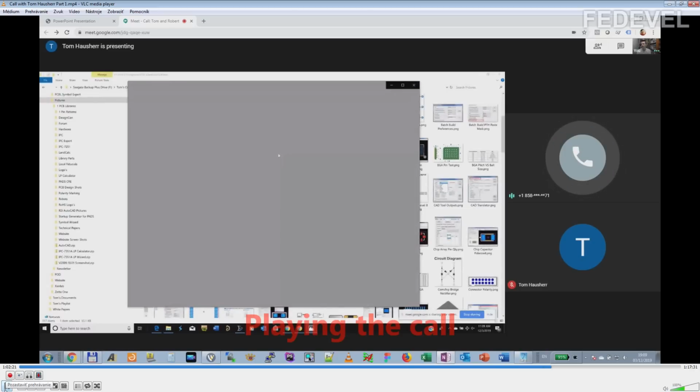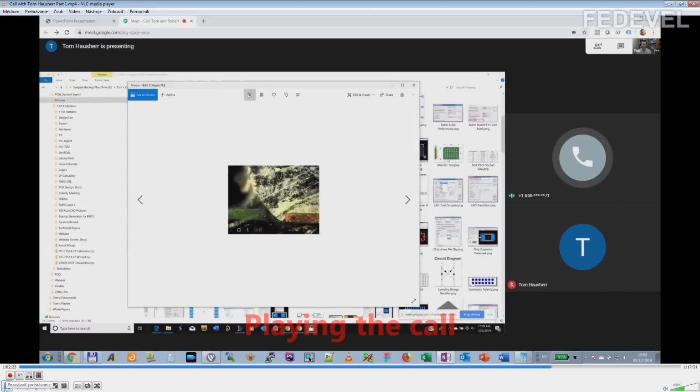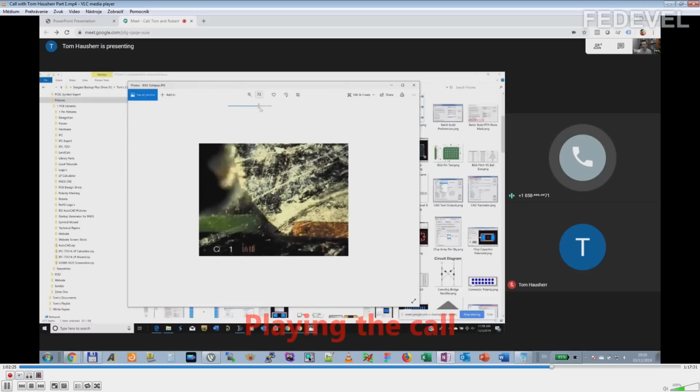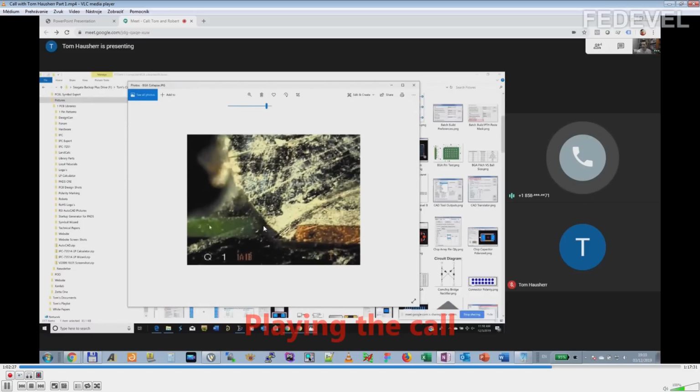You want a BGA to collapse around the pad, so you have here your solder mask, your green solder mask, okay, and your pad is much smaller than the ball, okay. And when you go to the oven, you want the BGA to collapse all the way around the perimeter of the pad to grip that pad. So you pull the solder mask away, okay.